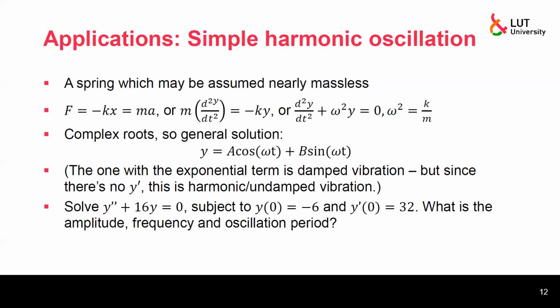And it's now half past, so let's have a quick browse through of this example here. One key weakness on this formula compared to reality is if you're having really beefy springs and small masses, then this example assumes all the mass is on the end of the spring. So it's not exactly correct physically, but when we're having relatively light springs and heavy masses, it gets close enough.